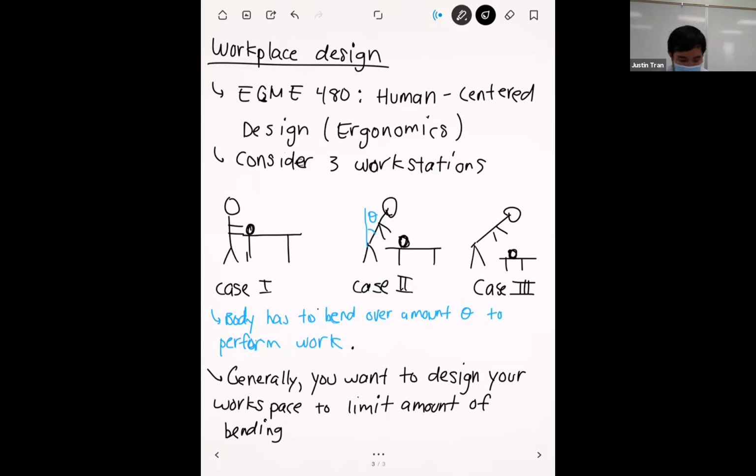Yeah. All right. Any questions on this before we start working on the numbers? Okay. All right. And so let's start with the free body diagram to show all the weights in action. Let's do just a simple 2D analysis, and let's assume that the entire torso is a stick. At the bottom of the stick right here, we have the spinal joint. That's going to be the focus of our analysis.